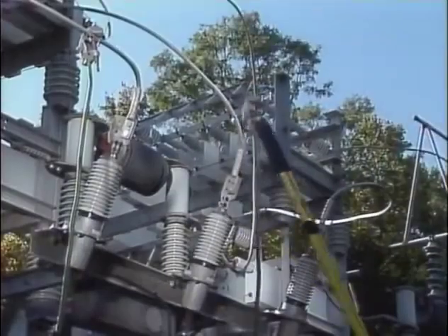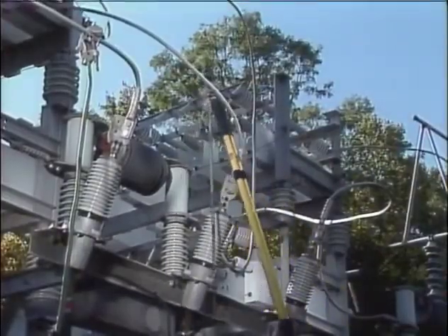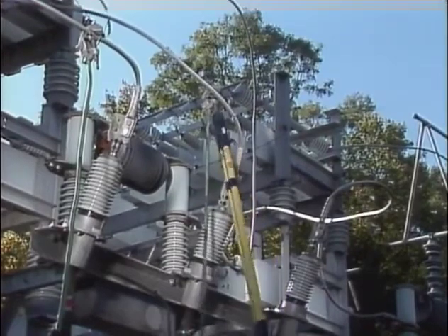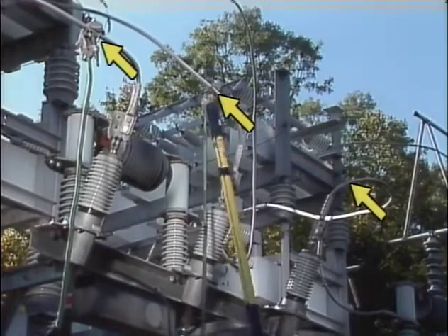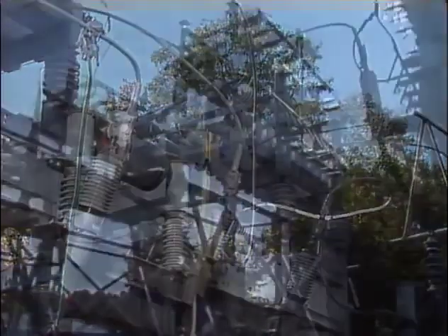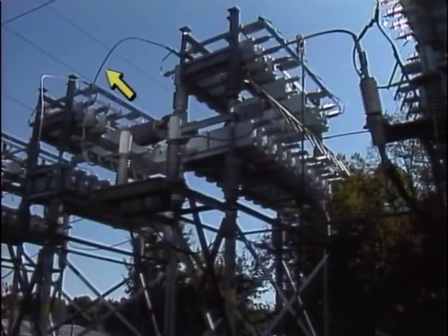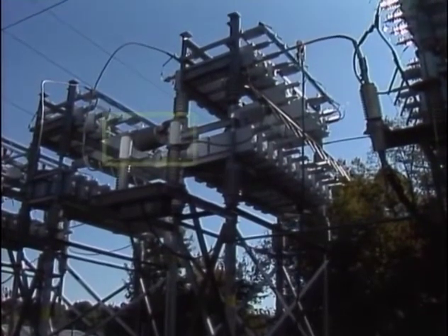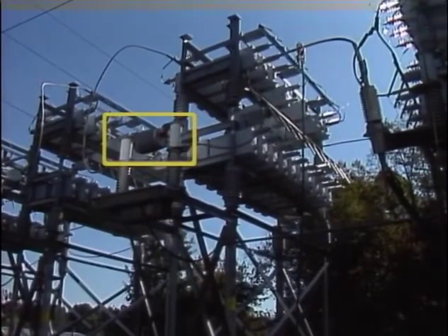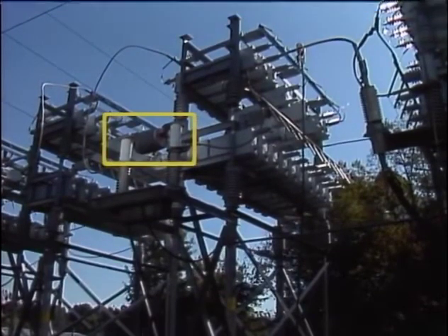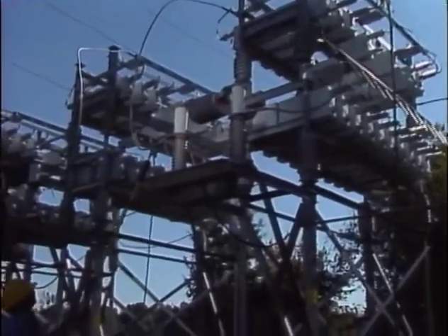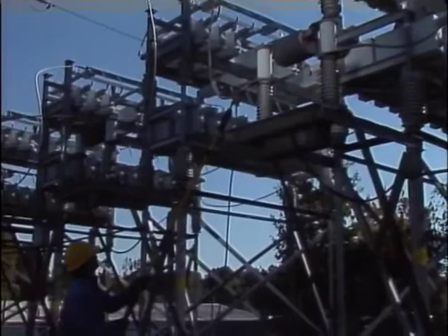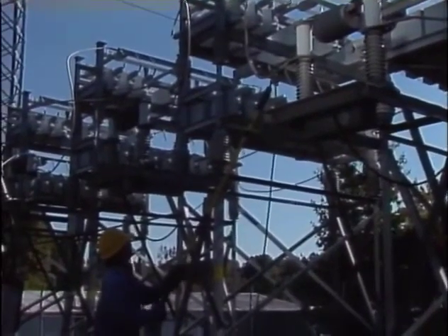Next, the source, or normally hot side, of each tier is grounded. For the lower tiers of this bank, this involves applying grounds to each of the three single-phase source leads that connect directly to the lower tiers. A ground is also applied to the lead between each vacuum switch and upper tier. With a vacuum switch, there is no direct, visible evidence that the switch is closed. If the switch were open, the upper tier would not be connected to the grounded source lead. Applying a ground between the switch and the upper tier ensures that the upper tier is grounded even if the switch is not closed.